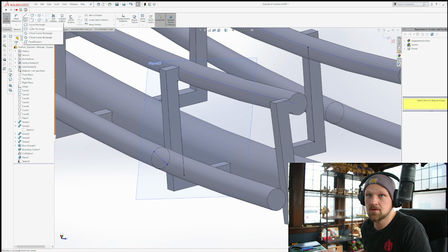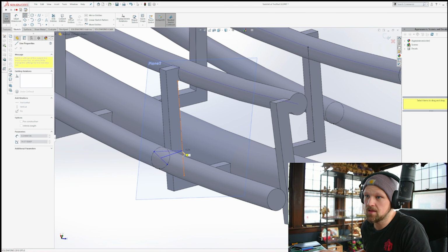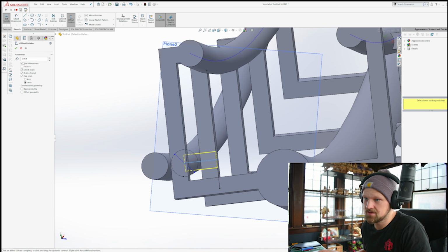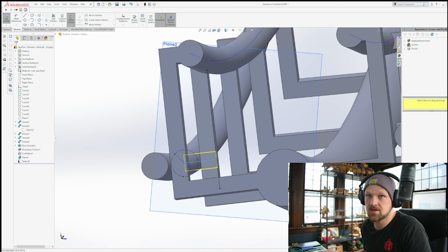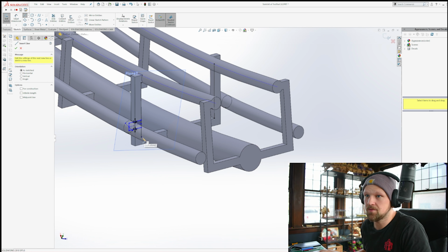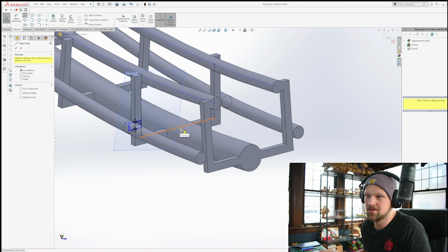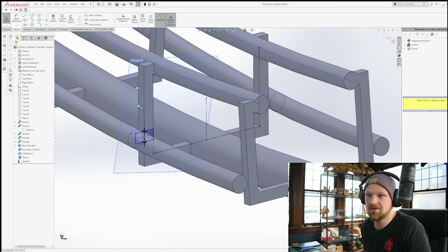So you got your perpendicular, and then you can just draw a line from here, and then just make sure everything's perpendicular. There it goes. So snap perpendicular, and then you just do offset. Make sure you cap your line. See what it's doing here. Make sure it's centered, and hit OK. Oh, I gotta mirror it, so let's do that really quick because it will be the same height on the other side. So I guess you only have to do it for one rail, not necessarily two. Just make sure everything's perpendicular, and it'll come out great.